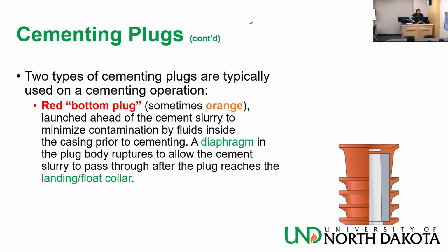Now, the bottom plug is very different from the top plug in that it has this little membrane here. It's a diaphragm. It's very easy to rupture, to break. You just apply pressure above a certain level and you break that diaphragm. And this lets you pump through it, okay?